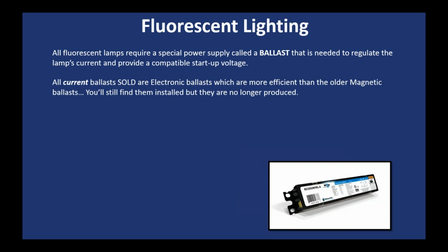Now, the old ballasts were magnetic ballasts, very heavy, very awkward. They cost a lot, but they actually work pretty well. You won't find those being made anymore. They're not being produced. All of the current ballasts that are being sold, most of which you're going to replace, are electronic ballasts. They don't work quite as well as magnetic. They don't last quite as long, which is another reason to start switching some of this stuff out.